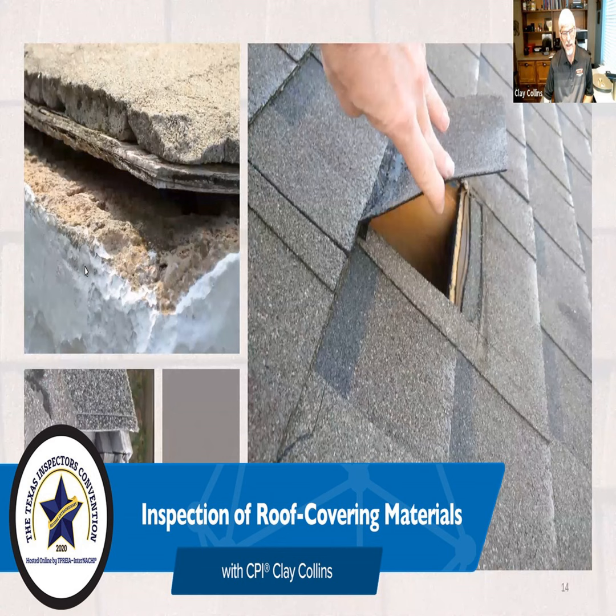And again, I told you a while ago that flashing is one of the places that is most often the source of the water intrusion. It's intended to keep the water out, but if it's improperly installed, that becomes the source of intrusion. Weather, we have the wind, rain, and hail.